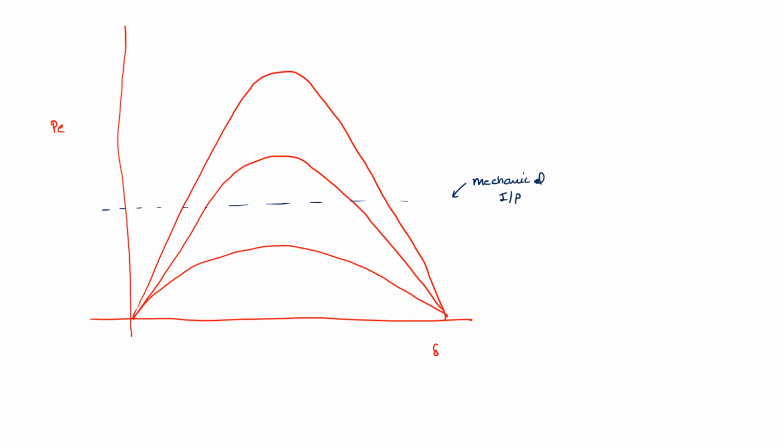Very important point. Let us consider this point A as the initial operating point, and it corresponds to an angle. Let me say this is delta 0. From the pre-fault curve, this point A has coordinates delta naught and 1. If I recall the pre-fault curve equation, it is equal to 1.67 sine delta. So I put these in this: 1 is equal to 1.67 sine delta naught.